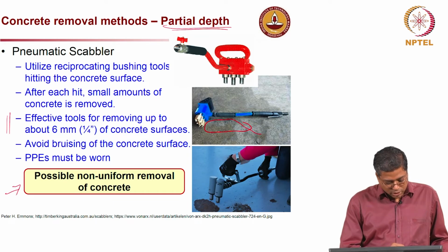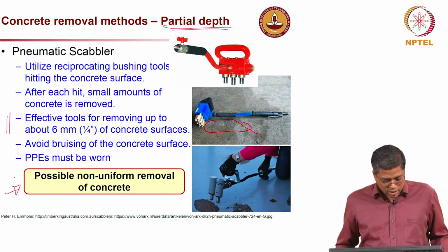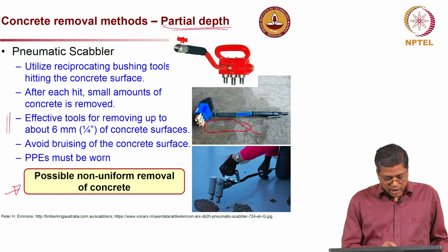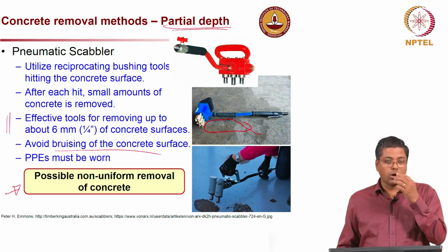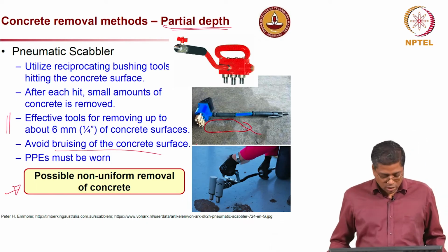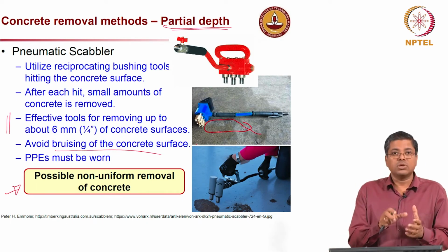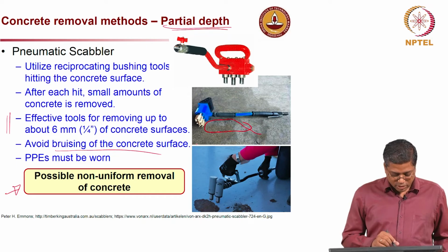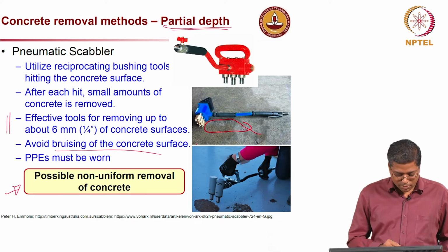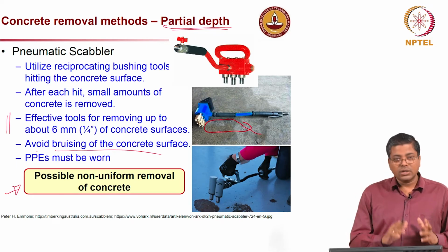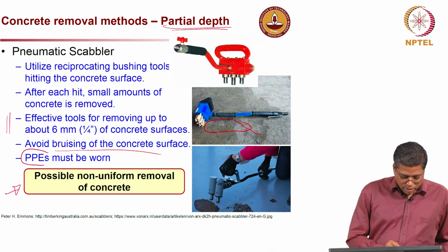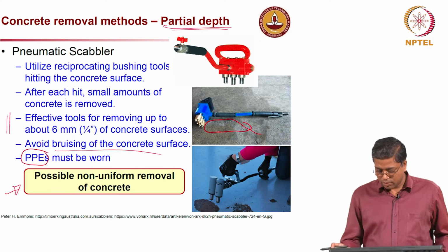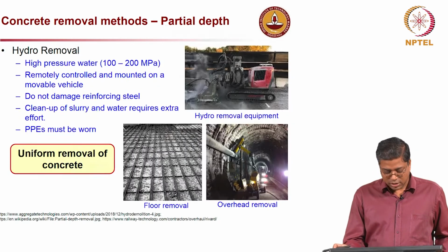Again, there is a possibility of non-uniform removal, and unwanted concrete should not be removed. You should not cause bruising of the concrete surface. That depends on the amount of time you apply the tool at the same location. And again, with all these power tools, we must wear proper personal protective equipment. So, PPEs must be worn.